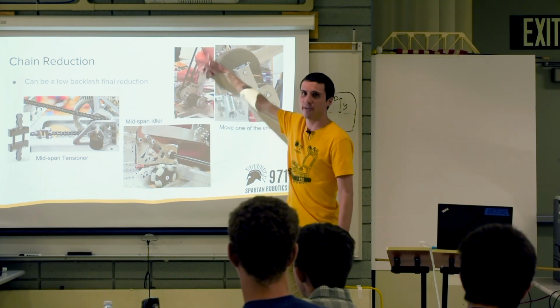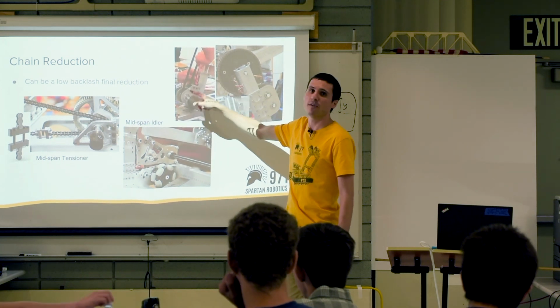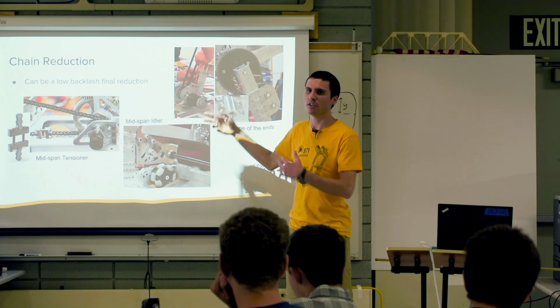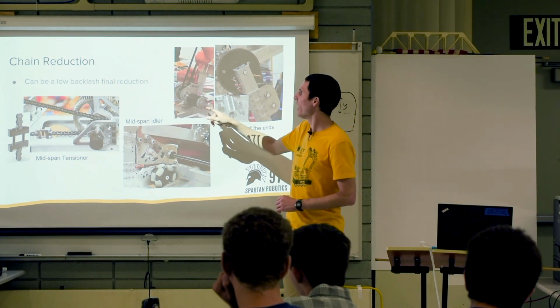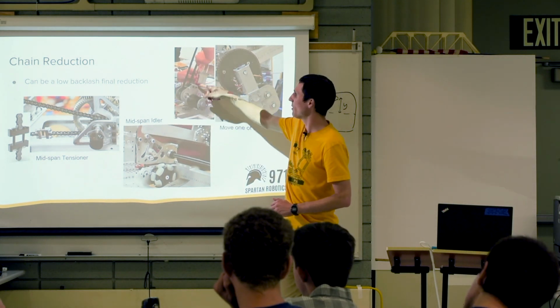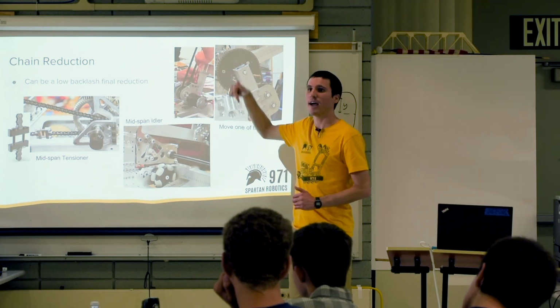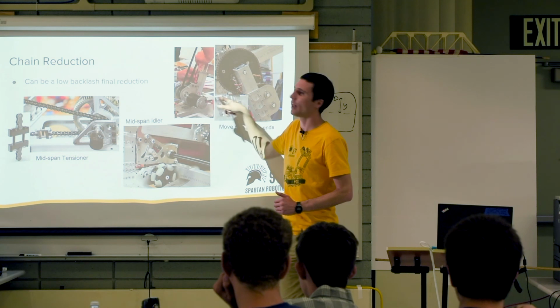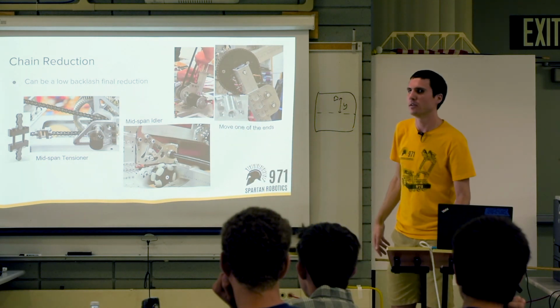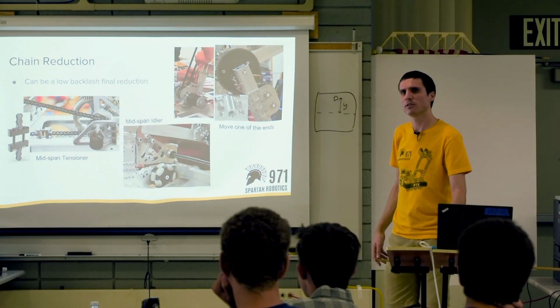And then here, this is the other side of the equation. This is on that belt on that same robot. We could move the other side of the gearbox. You could slide the gearbox along the tube. If you'll notice in this picture, someone is taking a wrench and pushing on the gearbox to slide it down the tube. Once it's tight, we clamp it to the tube. Does that make sense? Okay.